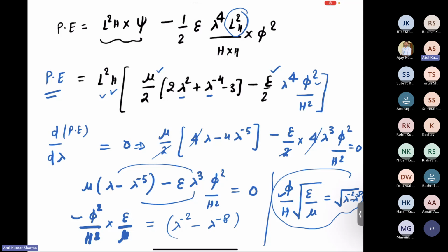that is lambda. So here one thing that you will observe is that the relationship between phi and lambda is not linear, like for a spring case F is equal to Ku, that was a linear relationship, but here you will find a non-linear relationship. Another point that I want to tell you is that this relationship corresponds to any equilibrium. It may correspond to the stable equilibrium or may correspond to the unstable equilibrium. Okay, because here we have taken up the first derivative only.